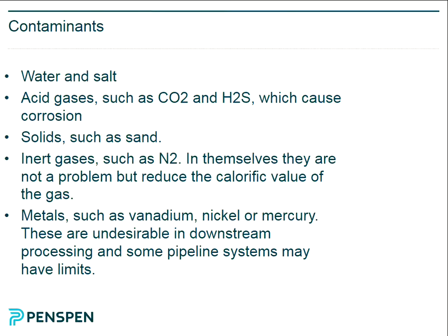You can work out the partial pressure of CO2 if it's more than a certain amount. I think it's 5 bar, or 20, I forget. There's a simple formula for working out the corrosion rate of CO2, so you may end up having to inhibit or even use exotic materials. So yeah, it is a trade-off, definitely.